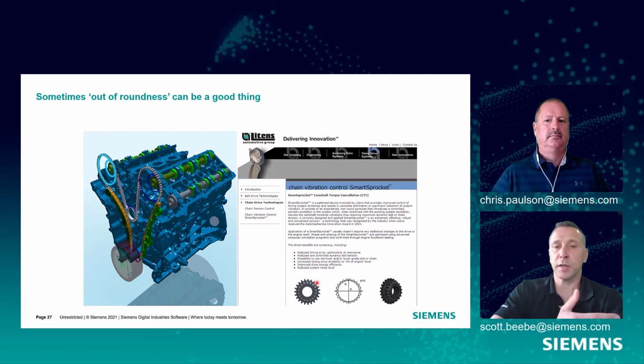So that's an upgrade you can get with a bicycle, and they tout the same benefits, where you get increased chain tension or belt tension when you are pedaling with an oblong gear. So it's not always a bad thing to have this oblong gear, but it will manifest itself in the data as a plus or minus second order based on that force interaction that Chris explained per rotation.